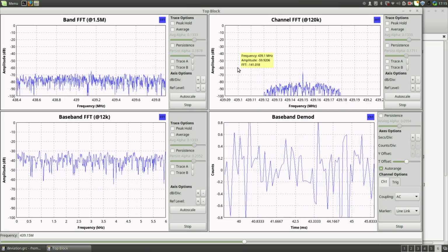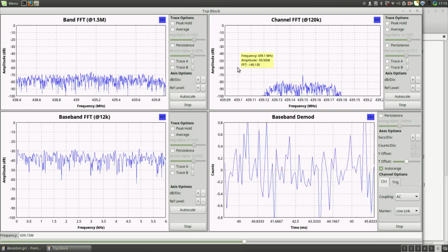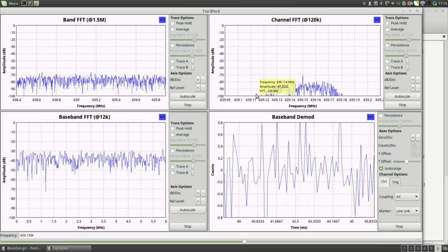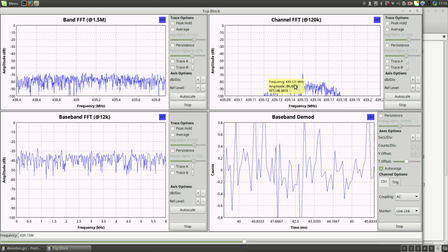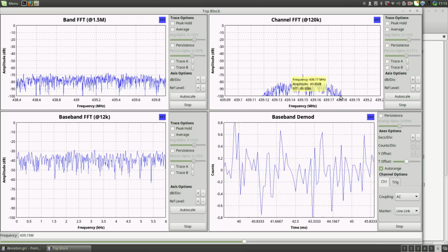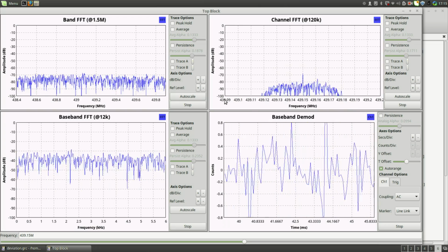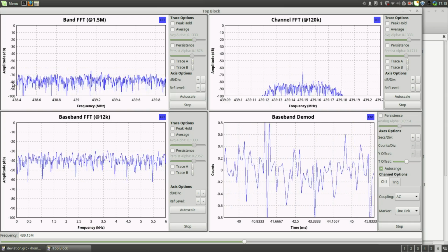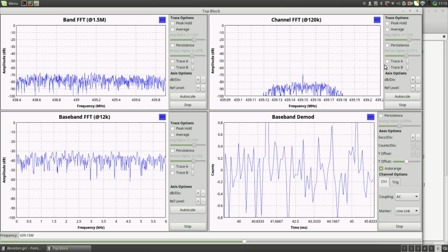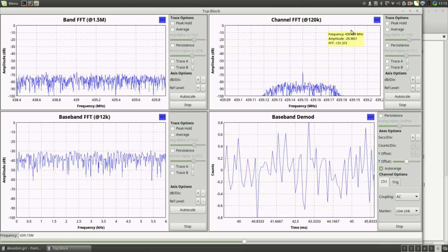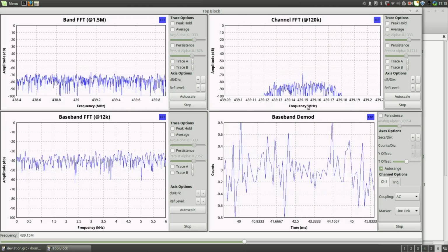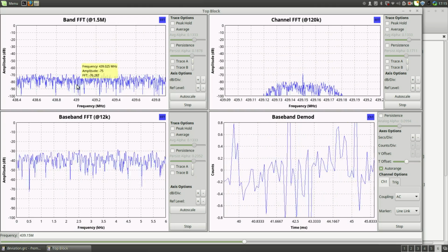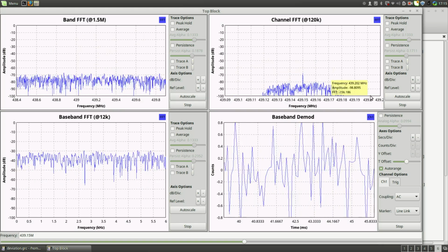Of course, it's filtering everything, so if I inject a signal that is out of band, it would be attenuated equally. But since this is not happening, I'm not transmitting anywhere, it's just noise that is attenuated out of band. And lastly, if you look at the frequencies, that's a span of 1.5 megahertz here, and here we only have 120 kilohertz. That is due to the resampling, and this will allow me to see sidebands here that I won't see here, just because the resolution is higher.